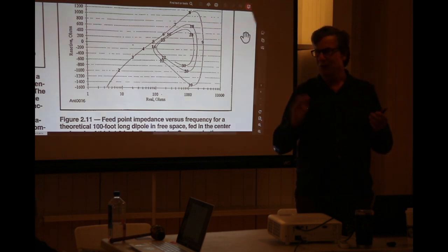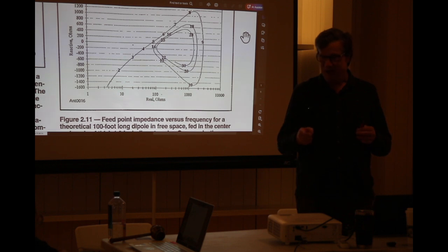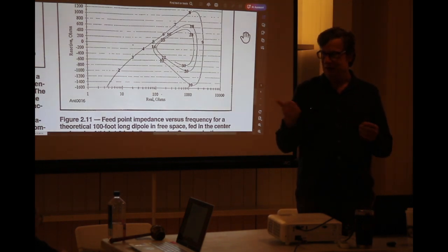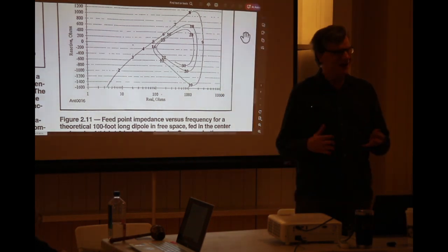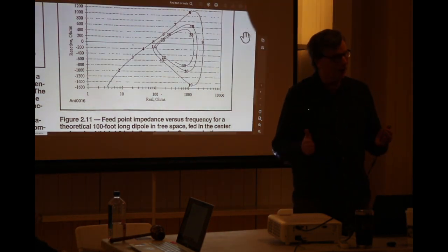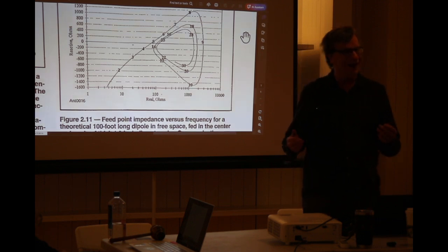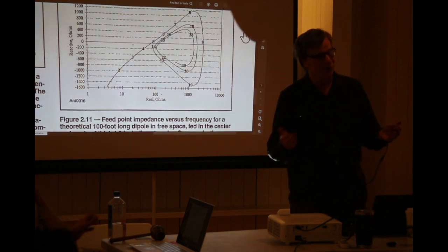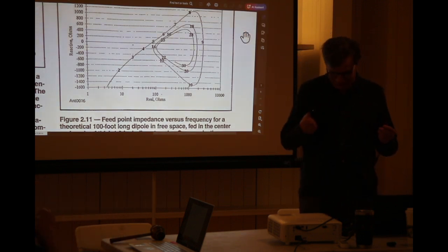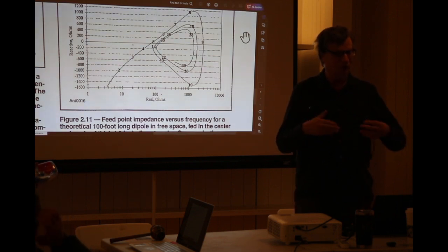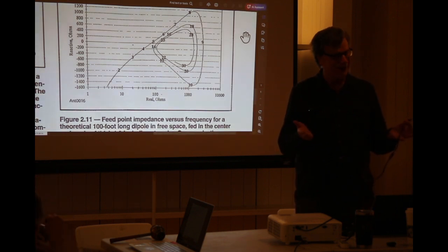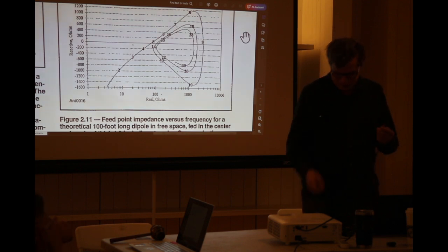How many are using open wire feed line? Okay, so with the calibration procedure, you just calibrate with a 600 ohm line, and then everything's going to work right there. That's something they don't tell you. But now you all know that there's no comprehensive instruction manual for the manual VNA. You have to figure all this out online, but some of us old timers who played with the old time VNAs know about the calibration procedure and why you do it.